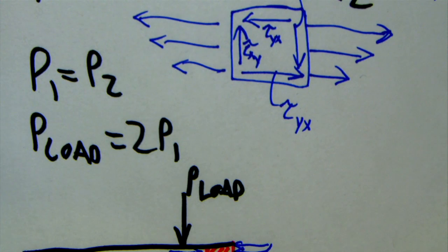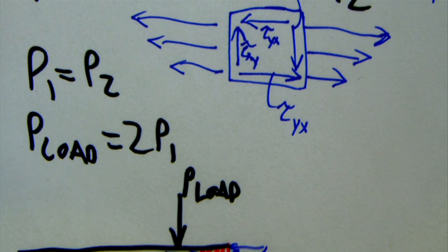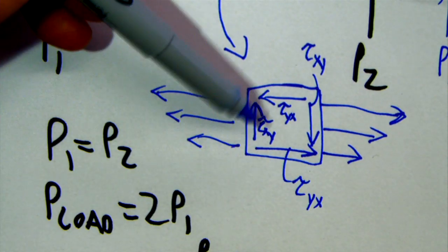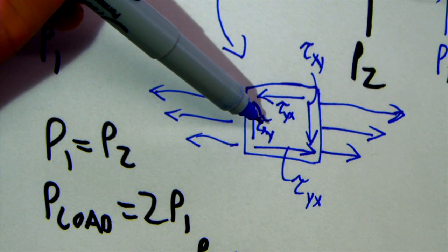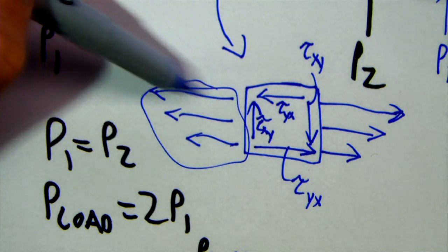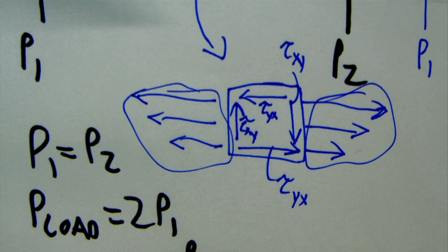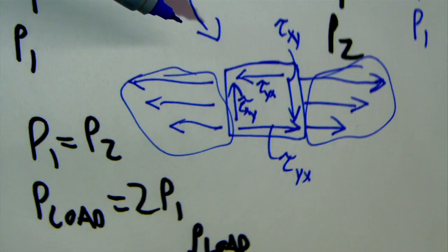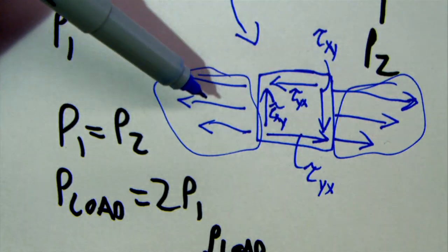We got vertical forces, we also got horizontal forces. And we know that sum of forces and sum of moments on this stress cube are 0. So if I say that these horizontal guys, we know that those are equal and opposite at a point, because it's bending. So those are all going to equal out.